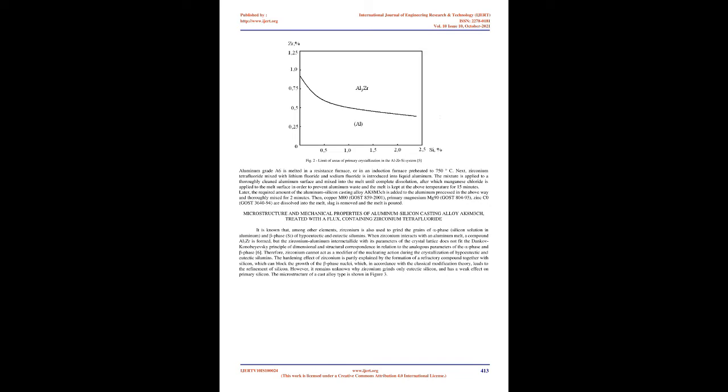Taking into account the high chemical activity of aluminum and magnesium, which are used in the preparation of the alloy, the contamination of the alloy with solid and gaseous nonmetallic inclusions should be expected at all stages of the technological process. To prevent contamination of the melt, preparation of equipment, working tools, and materials is carried out. The crucible is visually inspected and its suitability for melting is determined. The crucible is cleaned of dirt and slag, painted with a protective paint based on zinc oxide. The ladle and mold are also painted.